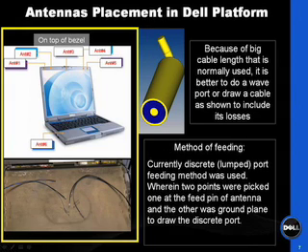But in a mobile phone, most of the people are now aware that you have antennas which are quarter wavelength, and you use the ground plane as the image. So you have quarter wavelength and the image quarter wavelength, so it's half wavelength, and it works very fine. That is, the ground plane also acts as a part of the radiator. But in a laptop, the situation is not that good, because the ground plane, if you take this magnesium frame, most of the laptops sometimes have a magnesium frame, or you can use the LCD display, this is all metal. Now this metal is quite big, bigger than quarter wavelength, so it cannot function like a ground plane. It's not like a part of the radiator. In fact, it's more like a reflector.